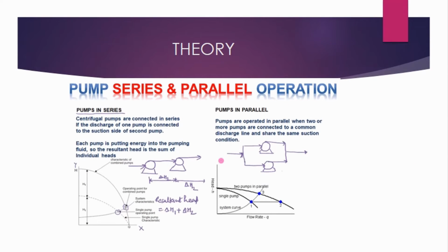So for theory, the pump is a mechanical device placed on the pipeline network that converts mechanical energy supplied from an external force into liquid flow from a lower potential to a higher potential. This centrifugal pumps experiment has been set at a manual mode, making switching between series and parallel setup easier. The volumetric flow is based on the pressure generated within the pipeline when using series parallel centrifugal pumps. The volumetric flow is high while the pump pressure is low. The pump pressure is low while the volumetric flow is high.